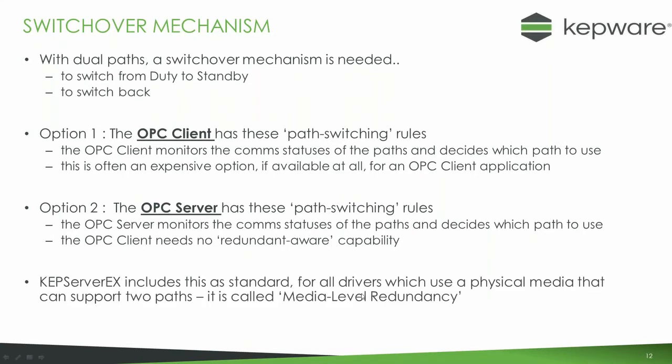And this is a feature called media level redundancy, which is included within KEPServer, and it's included for all drivers which can use a media which can support 2 paths. So all Ethernet drivers, for instance. So that's a feature which is included within KEPServer. It's no cost. It's part of the core. It's not a plugin you have to pay for or anything of that nature.